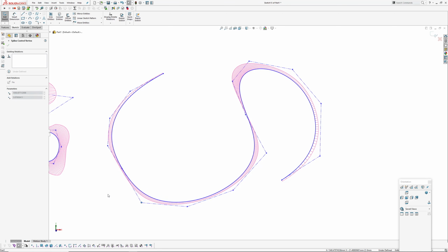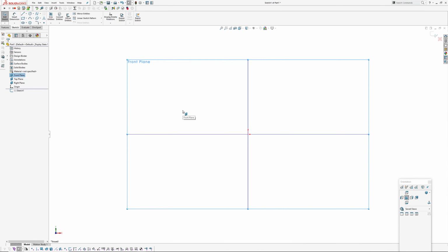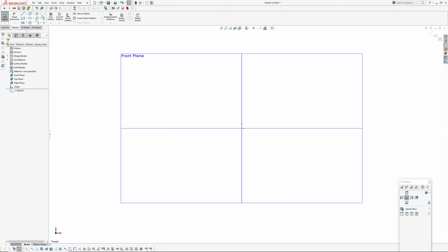So this has got G4 internal continuity, which is pretty smooth. You can have a long spline with lots of control points, and tweaking this end over here doesn't affect the curvature elsewhere. So depending on what you're trying to do, this could be quite useful. Right, I'll just cover another scenario where you're using a spline or an arc or something conic.